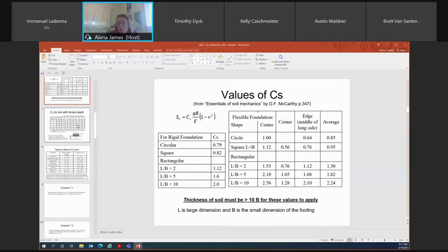So if it's a smaller clay layer, yes, you would go in and over excavate, and then place your material in 6-inch lifts and compact the material. We usually reserve that for thinner layers. 2 meters is getting on the high side. If you had a clay layer or another type of soft material that was less than 1 meter, you would typically go in and over excavate.